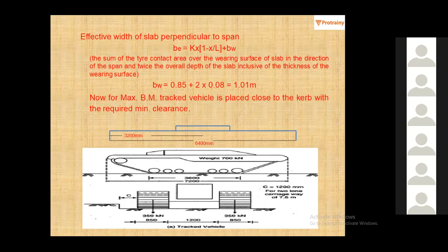Now, after design bending moment, you have to find shear due to the same load. We have to find shear. ठीक है ना? Now the same process we have to do for shear. Just arrangement of load is going to change. Bending moment के लिए load center में था. In order to find out shear, definitely load या तो आप यहाँ पे move करा दीजिए इस end पे, या इस end पे move करा दीजिए. ठीक कह रहा हूँ ना मैं? That is how you are going to find out shear force. सही बोला ना भैया? Shear center में क्या होगा? How much shear is going to be at the center?